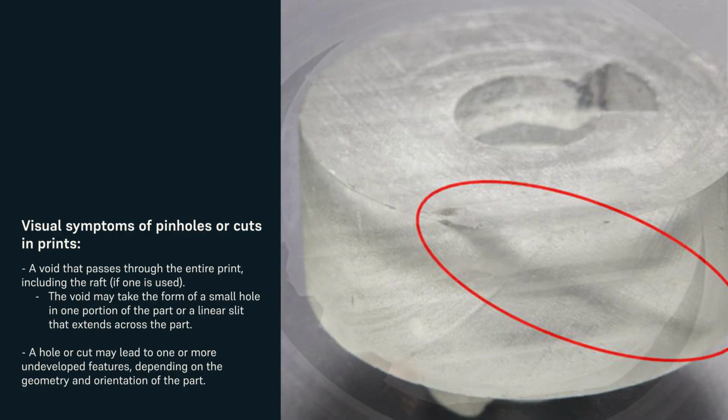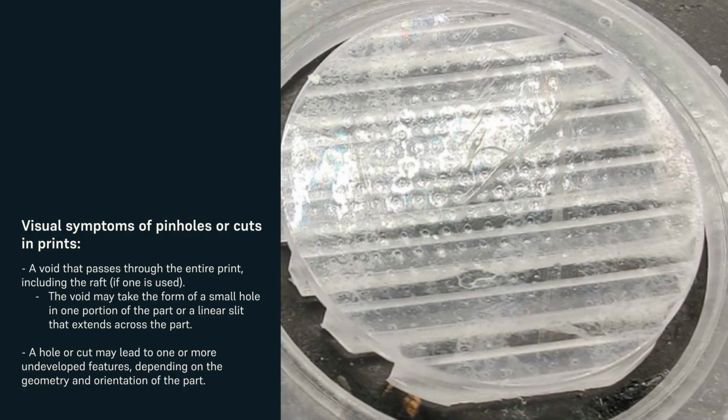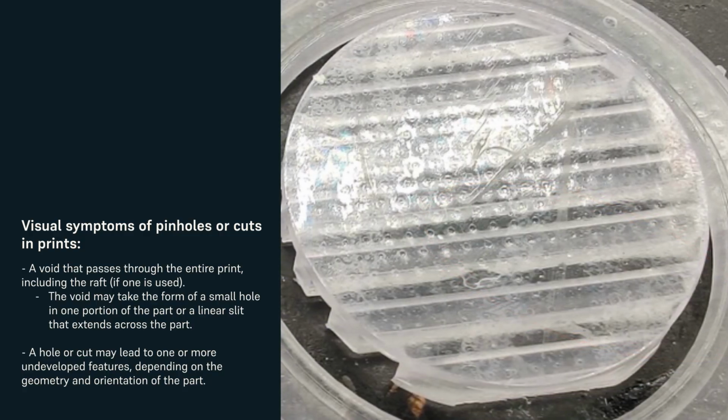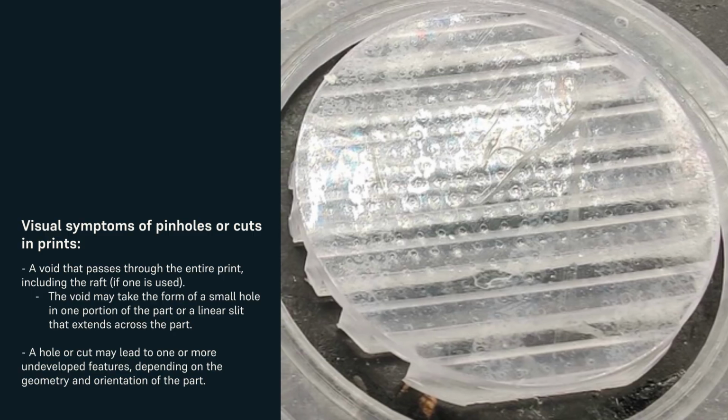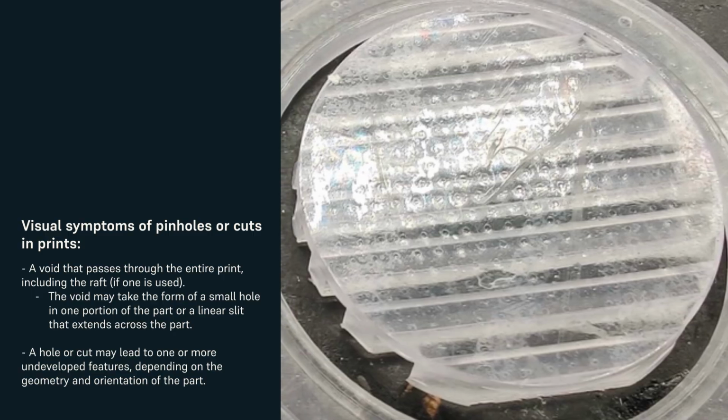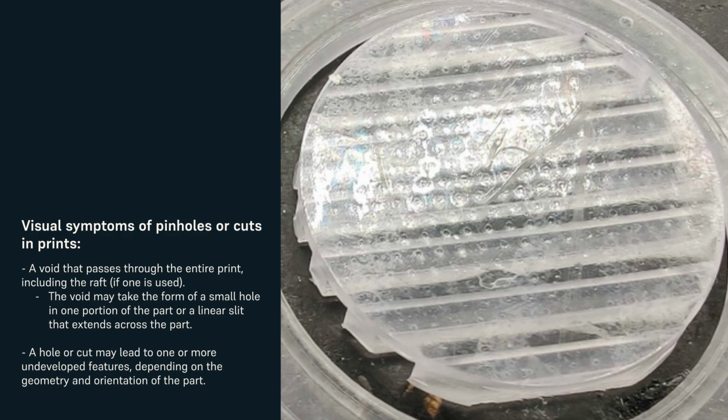A hole or cut may lead to one or more undeveloped features, depending on the geometry and orientation of the part. If while curing a layer, the light is blocked before it reaches the resin, that portion of the part will not form properly.